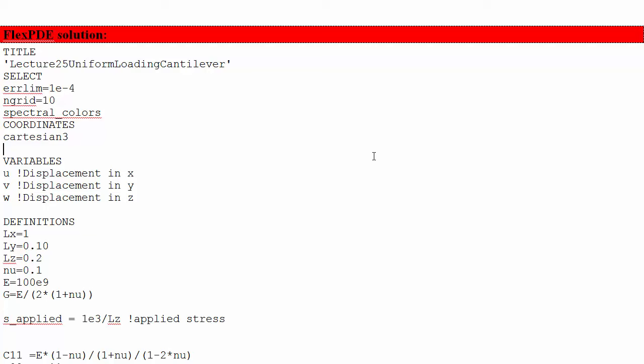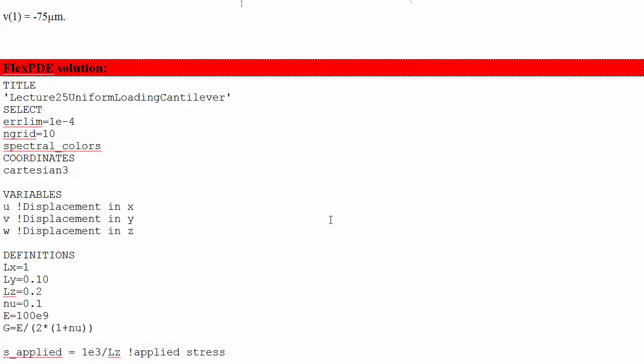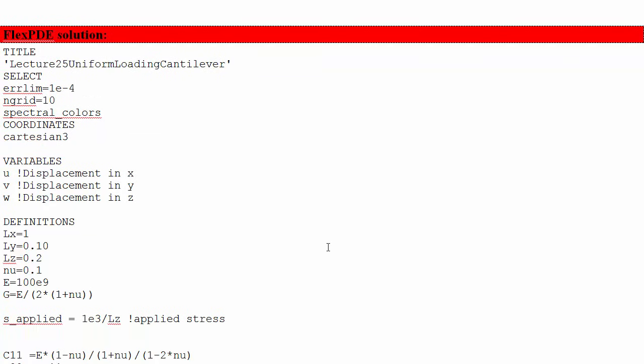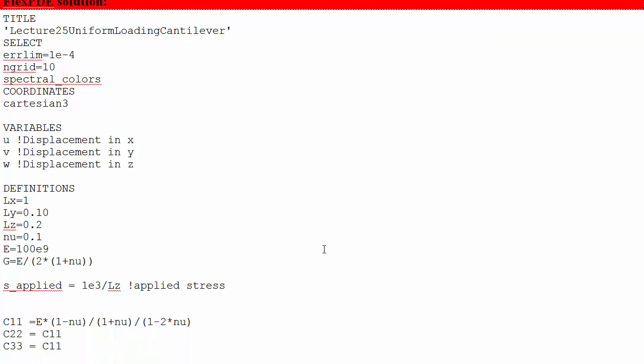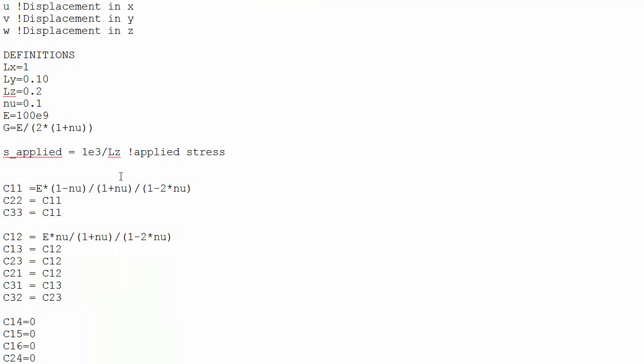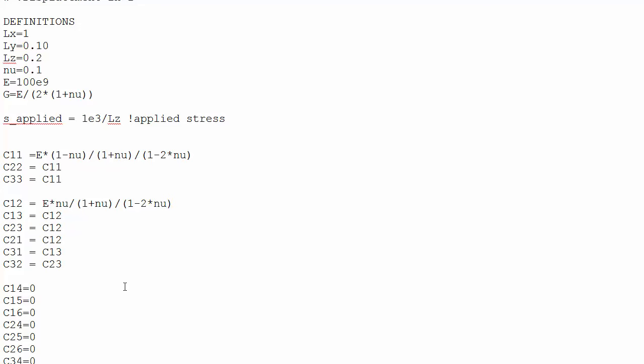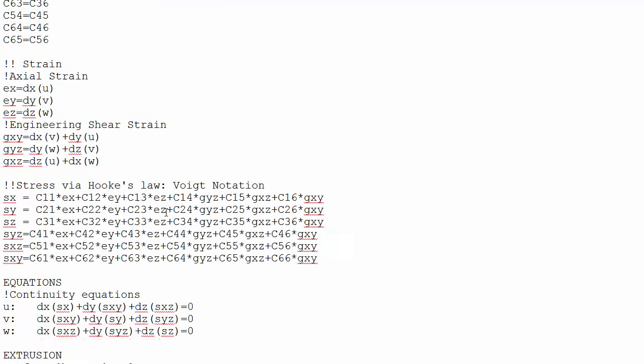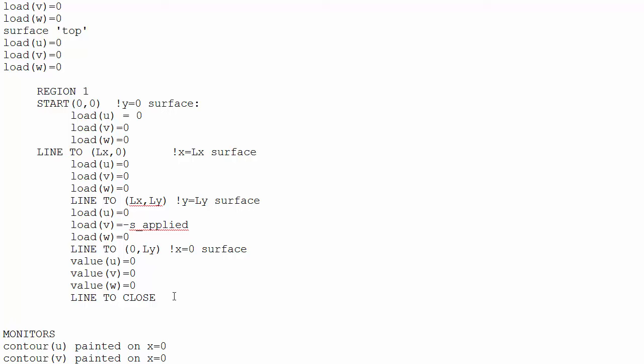After all of that, you'll be pleased to hear that solving it with FlexPDE is surprisingly easy. So what modifications do we have to make to FlexPDE to let it solve bending problems? Answer: nothing. Internally, bending is not doing anything different than the stress and strain that we were already accounting for with our equations. So all you need to do is apply the different boundary conditions.